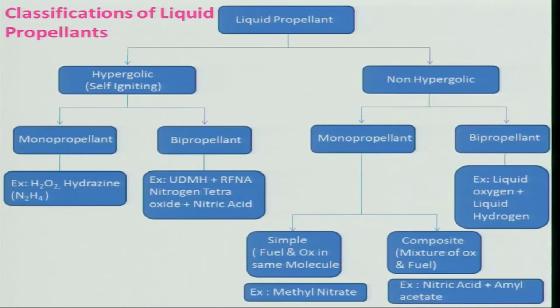Liquid propellants can be classified into two categories. One is hypergolic propellant, right. Hypergolic propellant means self-igniting. That means you need not give any ignition energy for initiating the combustion. Don't you think it will be very hazardous, right? Because if I have fuel and oxidizer, it will just start reacting, so it is a very dangerous thing to handle.